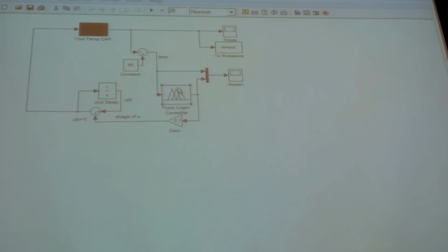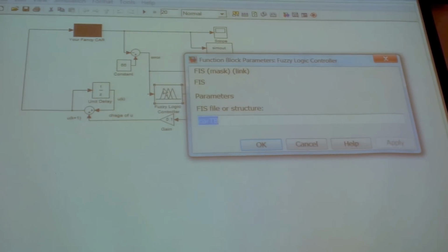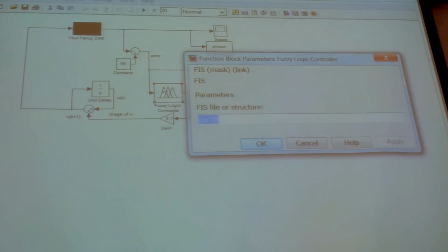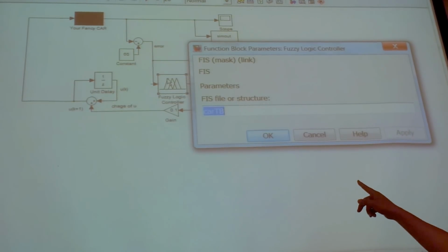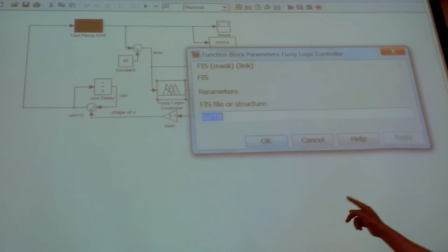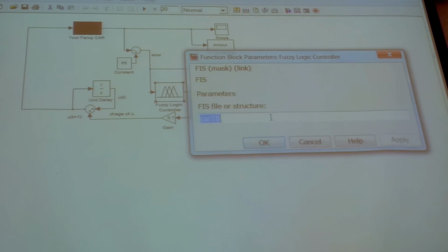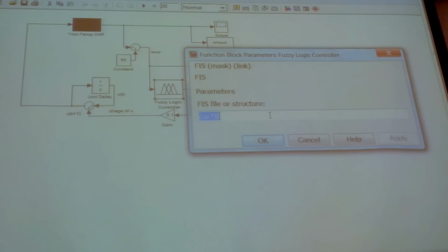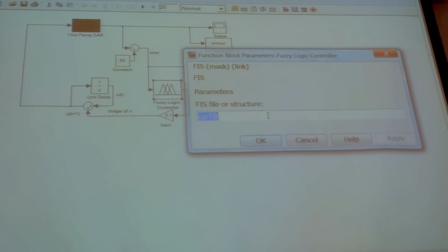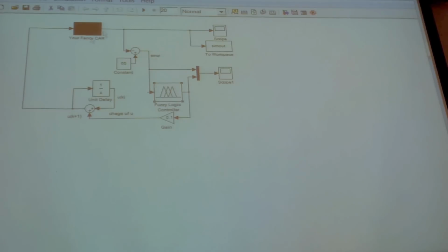Here, see? I have this because you have this fuzzy controller. This block, just like the ILS we used, is in the Matlab toolbox. You open Simulink, and you can find it in the fuzzy logic toolbox. You can move that fuzzy controller block in. When you click on it, just like the ILS, here is the controller function I used. The output is 75 and negative 75, so I have a gain there, 0.1.